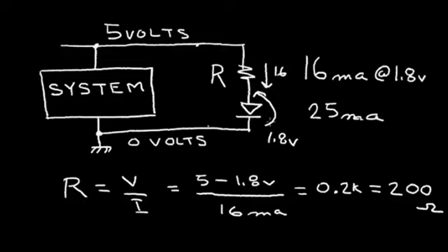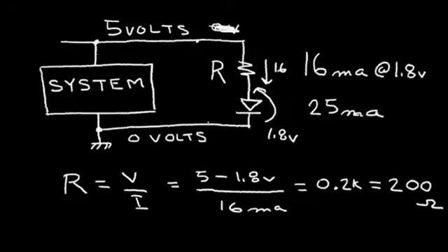Now if the power is off and this 5 volts goes to 0 volts, then I'll have no current flowing in the LED, and the LED will be off. So it seems like this should work fine as a power indicator. So let's evaluate this resistor. Now, in a way, I've lucked out. For 5% resistor tolerances, a standard value is 200 ohms.